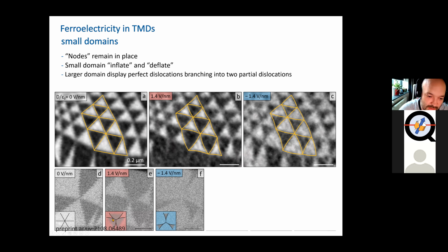You basically merge 2 partial dislocations to create a perfect dislocation in the middle. Because the Burgers vectors for these dislocations are pointing along the same direction, they would not be able to remove each other from the system, and you would always have this perfect dislocation left.